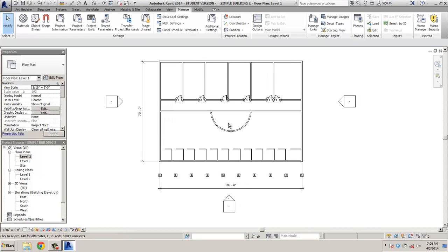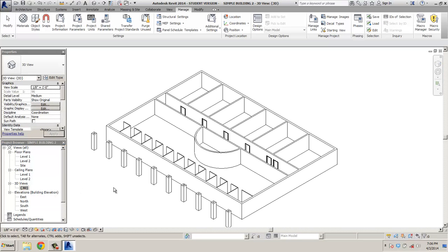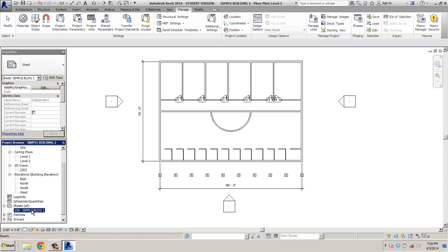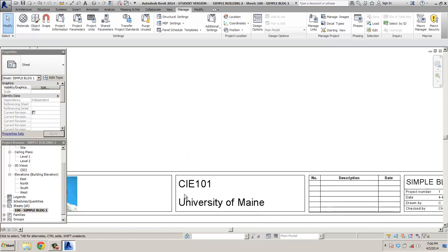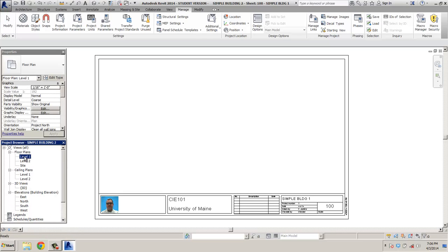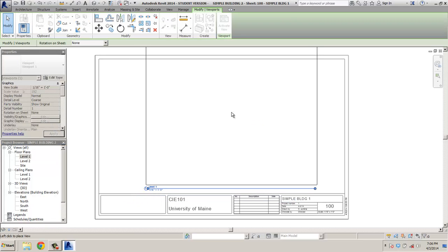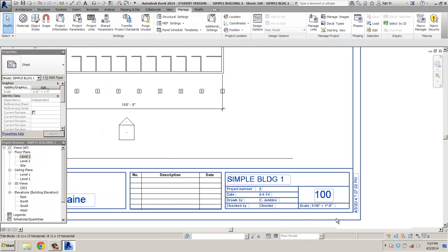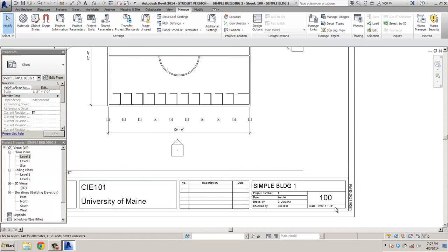So having this much of the building done, if I go to my 3D model again, there's our columns and our building and our cubicles. I'm going to go down to my simple plan down here with my sheet, zoom out, or just double click my mouse wheel, go back up to my level plan, floor plan, hold your mouse in and just drag it over and place it on here. I'm going to move this up so that my title's on the bottom, and there's my floor plan. You'll notice this populated down here at 1/16 of an inch equals a foot.